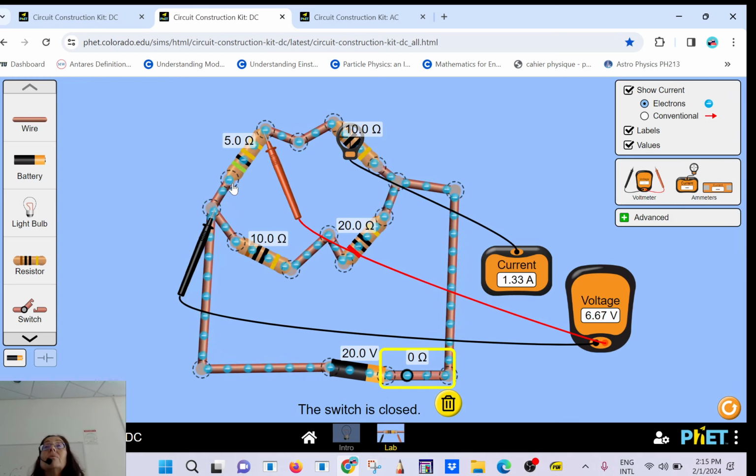So in Europe, they have a higher voltage. So that way, they don't need that much current, so they can save on the copper that they use in connecting wires. Okay? So again, the RMS, that's what you measure with your voltmeter, which is equal to 0.7 times the peak voltage. So if you isolate the peak voltage, you get 170 volt.